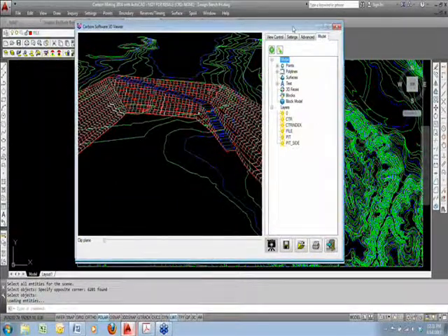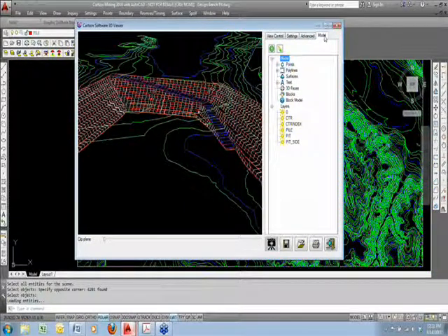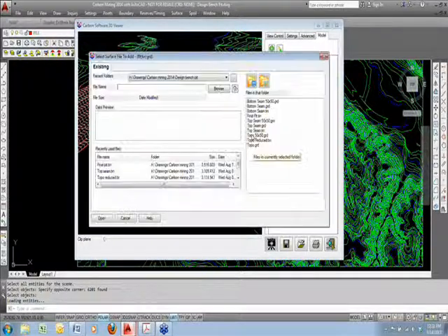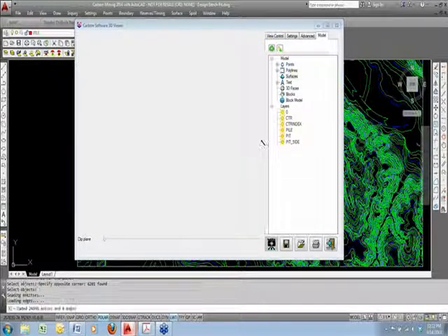One new feature, several actually, is the Model tab in this 3D viewer window. And what's kind of nice is that you can combine this line work from the drawing with now surfaces, and there's also ways to edit those surfaces. So let's go ahead and add. I'll bring in the topo tin. I'll do topo tin reduced.